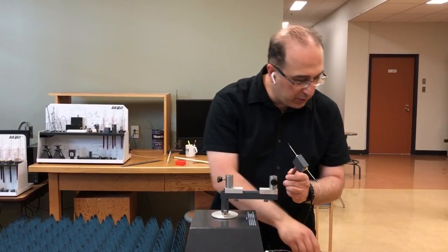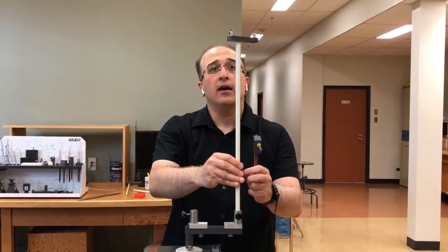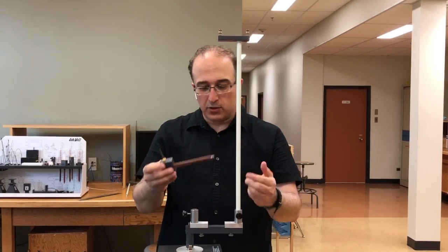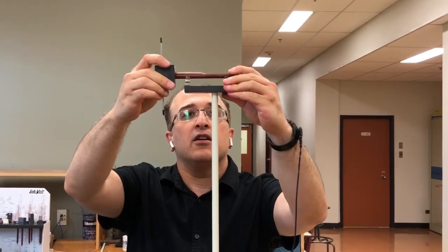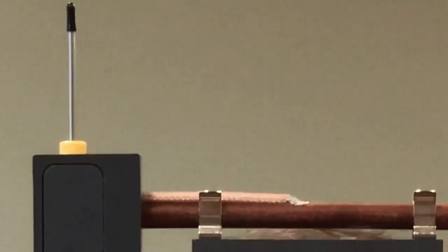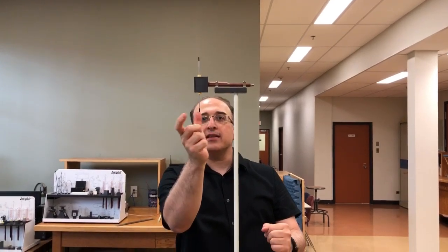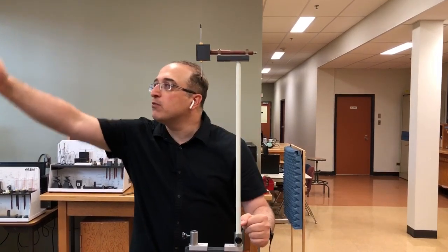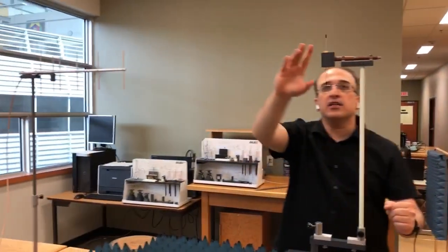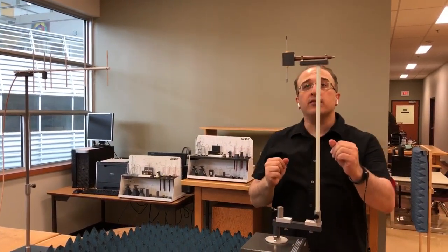What we're going to do is use a different rod this time, and that would be this rod here. Now this rod enables me to plug the antenna like this. If you look at this structure right now, if this rotates azimuthally, I'm going to be collecting H-plane measurements, and it's going to be co-pol because now this is also vertically polarized, so the polarization is matched. So if it rotates like that, I can measure my H-plane cut in the co-pol.